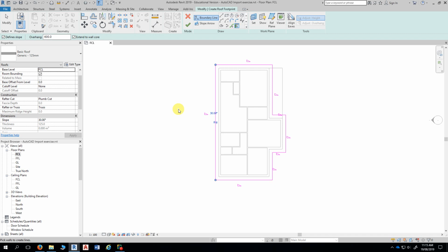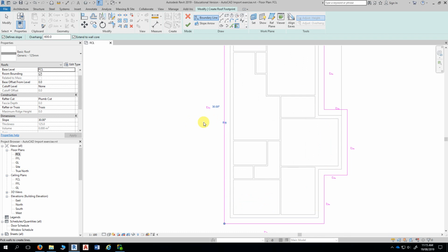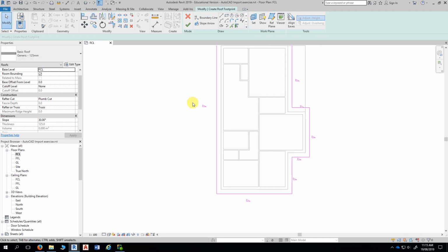Okay, is everyone okay with that? I want to give me a roof pitch too. It's giving me a 30-degree pitch. Yeah, now the thing is that as you place them, you can see that the sketch line has the pitch and it has a little right angle triangle here. The right angle triangle means that part of the roof is going to be generated at a pitch or a slope, and that slope is 30 degrees unless we change it.